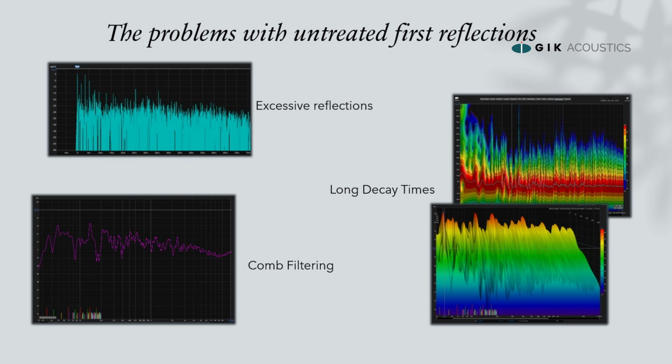The frequencies that are louder that we're perceiving in this frequency response graph are a constructive, additive thing that happens between the direct and the reflected sound. Areas where there's less energy are nulled frequencies, where that frequency arrives a little bit later, and the point that they both are at in that waveform determines that that frequency is not going to be heard, right?